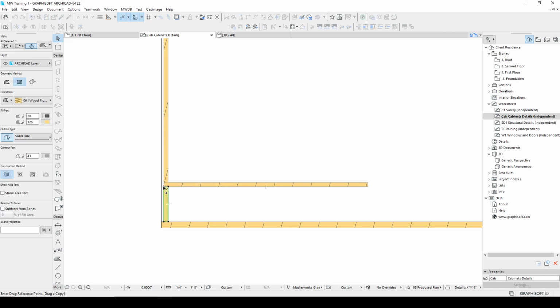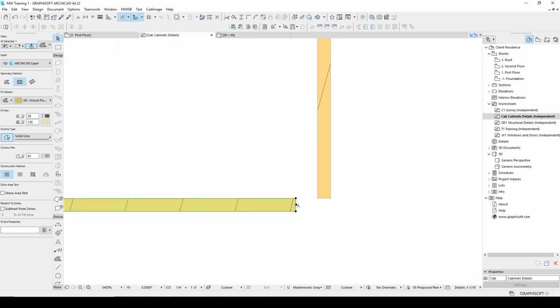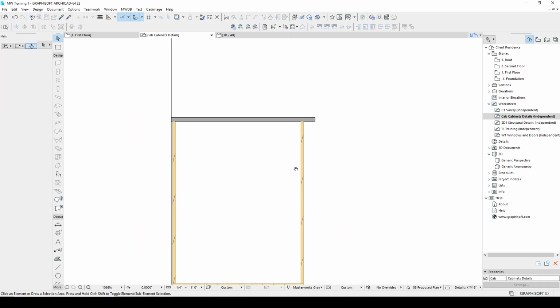And then I can bring this out, and let's go ahead and start by making a box that's 1 foot 11 3/4 inch, which is a typical dimension for a cabinet. An actual cabinet box is not 2 feet generally, because it doesn't make good use of the plywood. And then this would represent the front.